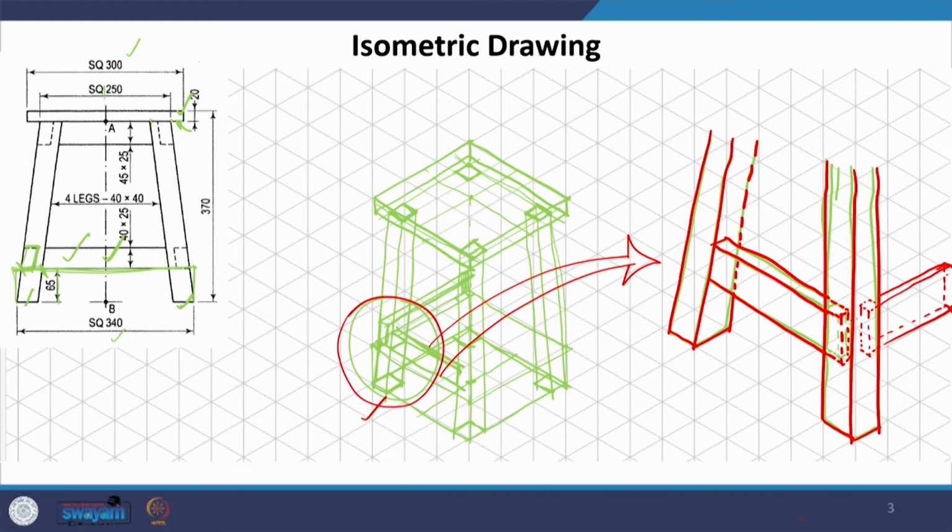So, this is how this portion is going to look. Exactly the same thing will happen in the top, but a large part of it is going to be hidden underneath this square part, because this is the top part. So, when you draw, you must try to draw all the dotted lines in place. Okay. If I do not draw any dotted line, this is probably what we will be seeing, only the solid part, and this will actually be tucked in beneath the top square.